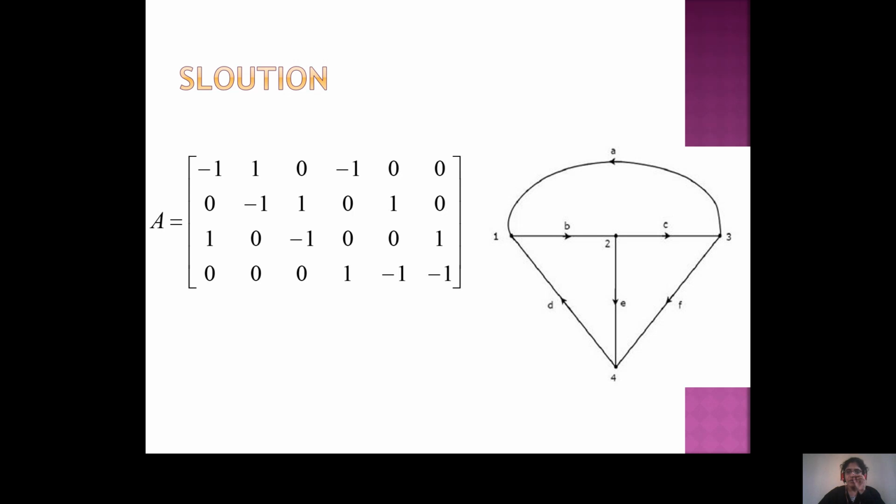So here we have to write down this in the form of the rows and the columns. When you write down the incidence matrix, first, if you observe, the first node must be there. For the first node, how many branches are related? A, B, D are related to the first node.